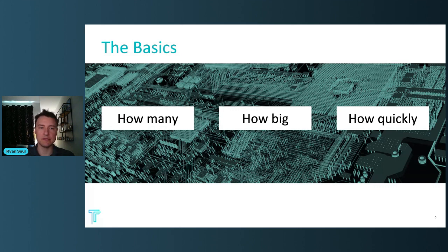I know, again, this is the basics. One thing that a lot of our customer engineers don't think about is maximizing fab panel space, which is to say that most fabrication panels are 18 inches by 24 inches. And depending on how standard your design is, it's actually very, very likely that your design will take up at a minimum an entire fab panel. So ordering quantity 1, ordering quantity 5, you're paying for the entire panel.